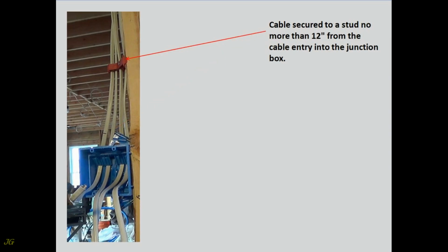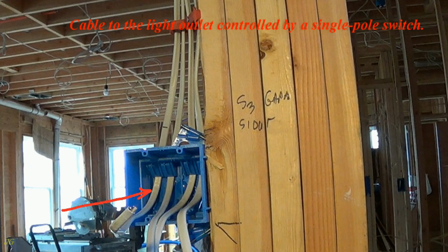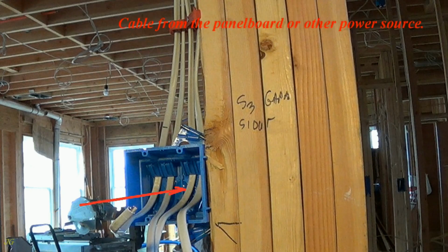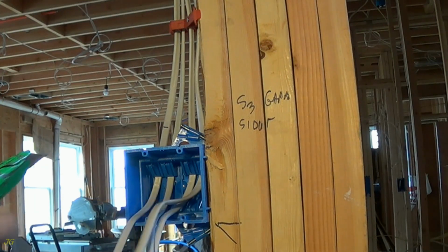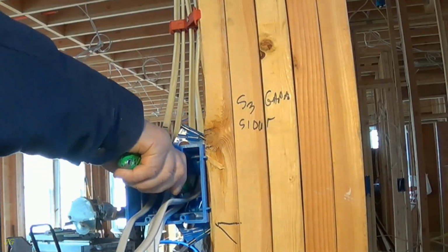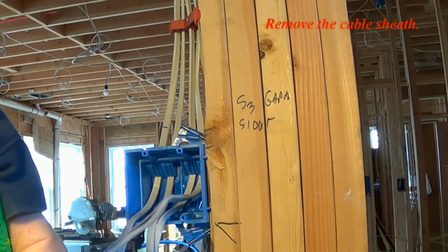Cable secured to a stud no more than 12 inches from the cable entry into the junction box. Spliced, connected, wires. Cable to the light outlet controlled by a single pole switch. Cable to another electrical outlet. Cable from the panel board or other power source. 14.3 cable to another 3-way switch, or 4-way if there are more than 2 switches. Remove the cable sheath.